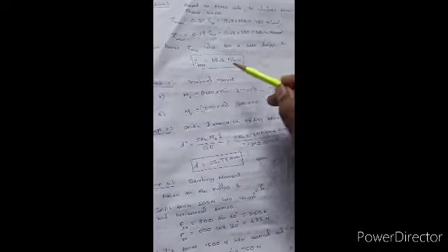So we have to use that as the permissible shear stress. For a safe design, the permissible shear stress should be the lowest value. So the lowest value is 68.4. So I will take tau max as 68.4 Newton per mm square. For a safe design, tau max should be the lowest value, and the lowest value is 68.4. Okay, I got the value.